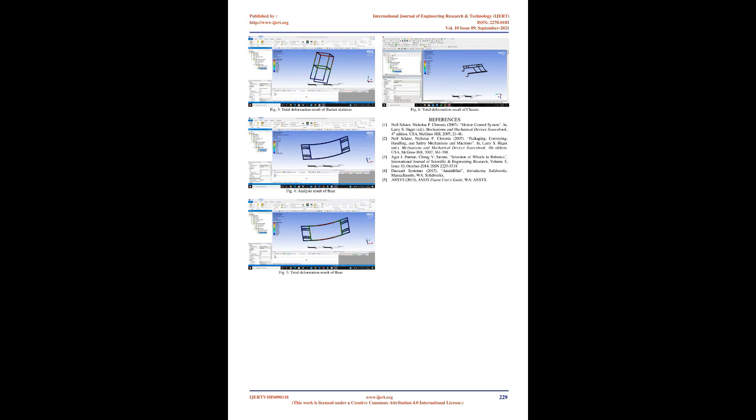Conveyor belt and support were given an inclination as a vertical conveyor belt would have required more power to take the ball vertically up, and weight was more balanced in keeping the belt inclined. Dimensions were decided keeping in mind the dimension of the ball and maximum dimensions of the robot. Inclination of belt was decided on the basis of its length, and part designs were modified during the assembly to incorporate the changes.